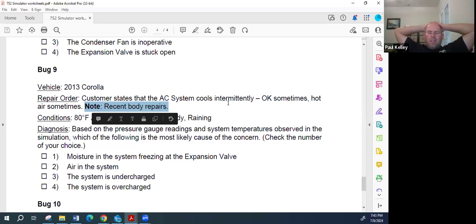Probably realistically, it needs a desiccant bag, receiver dryer, accumulator desiccant, something like that, right? Because that desiccant was sitting there absorbing that moisture all the time, and plus it was raining, it was humid, it was in the south, you know. That system is taking all the moisture it can handle, it's done. And now it's freezing up the needle.